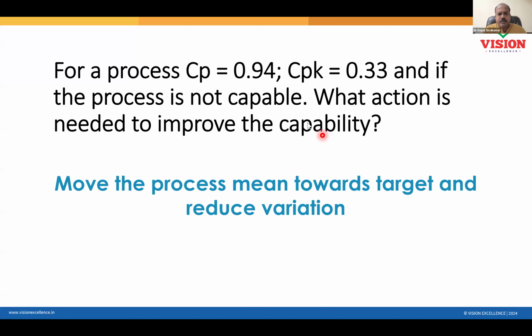Possible. All right, now answer this question. CP equal to 0.94, CPK equal to 0.33. Process is not capable. What action is required now?